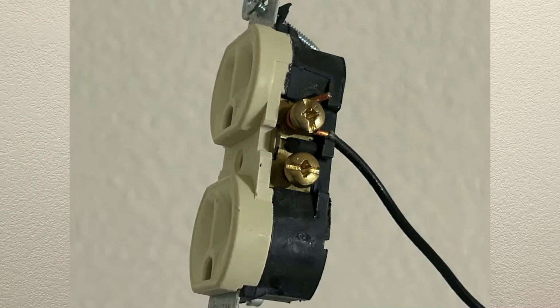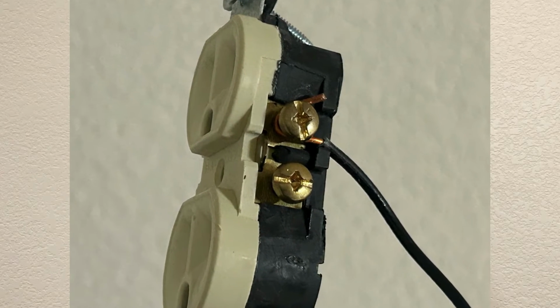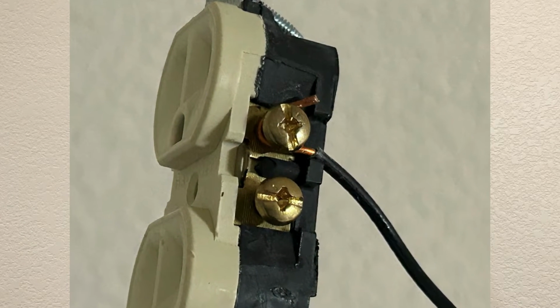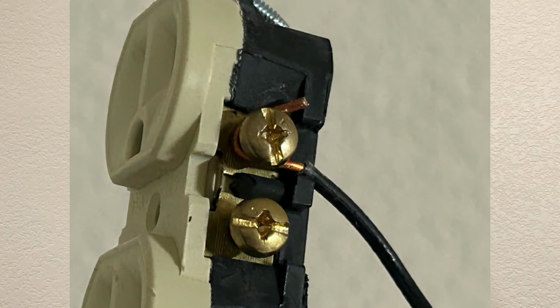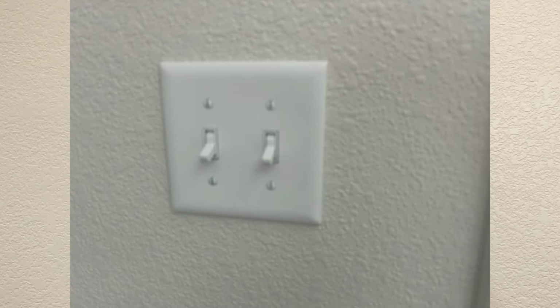Arcing can also occur when there's a loose connection, maybe at a light switch or an electrical outlet. The screw is not tight and there's a poor connection. Maybe you've heard buzzing on a light switch or an electrical receptacle. That buzzing is arcing occurring. Now, if you hear that buzzing, that doesn't mean that a fire is imminent, but it does mean that arcing is occurring and that connection needs to be tightened. Anyway, so you've got the two types of arcing, series and parallel.